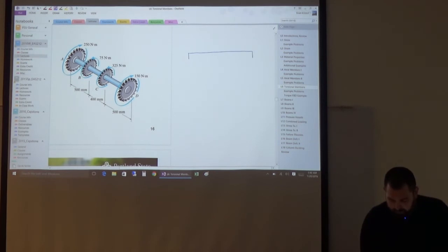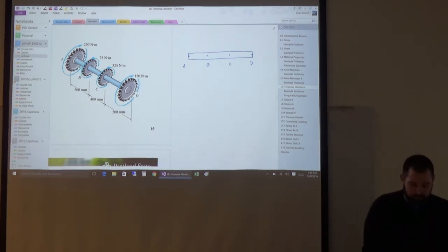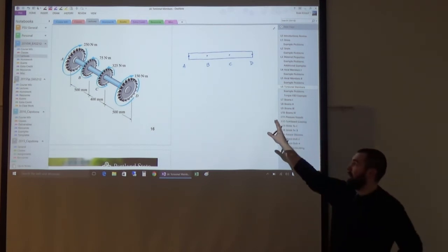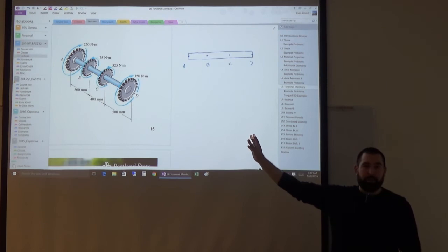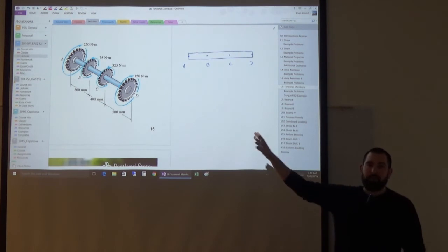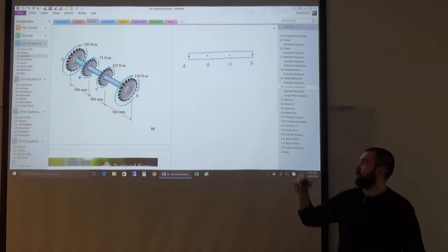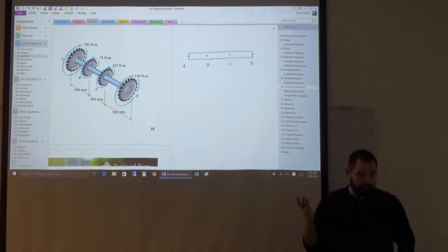And so here I'm going to redraw just the shaft itself, and we have A, B, C, and D. So I'll draw a point for each of those right there. Here the distances don't matter because it's not asking us about an angle of twist. It's not asking us or giving us a distributed load. But here, this is a two-dimensional free body diagram. Really try to avoid these isometric three-dimensional views when you could just as easily draw it in 2 dimensions, because, especially drawing on paper without the benefit of a lot of time and CAD, a rotation can start to look like 2 different directions potentially.